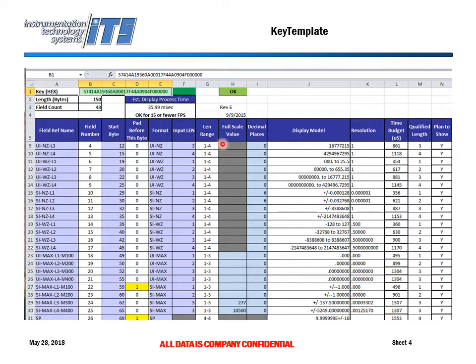And it's not scaled, so this is grayed out. It says there's no decimal places shown, so an unscaled integer of 3 bytes long would have a maximum value of 16,777,215 and with a resolution of 1 for the first bit of the first byte. So that's what this spreadsheet will do and help you construct and manage the display at the time of extraction of what this data looks like.